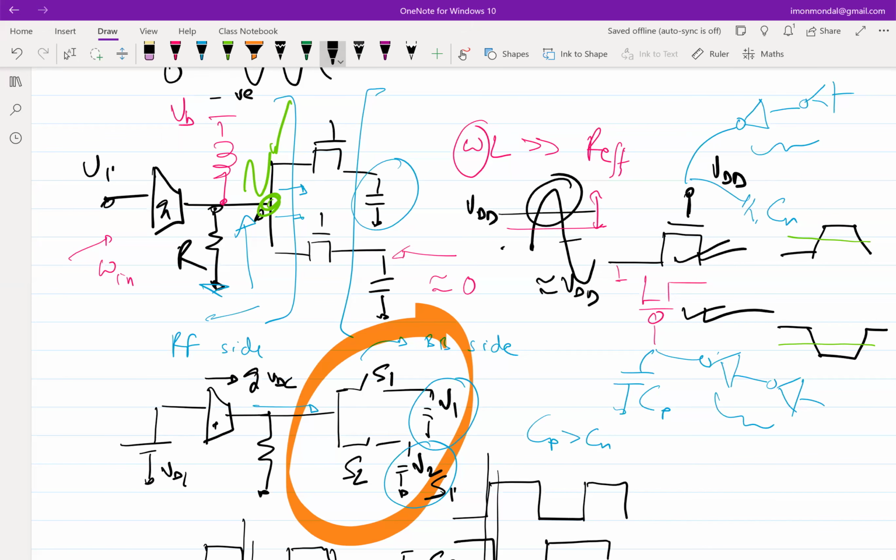Okay, fine. So the key takeaway is that it is better to use NMOS. Having said all of this, you can still use a PMOS transmission gate if you are aware of these things and taking care of them. But simply using it vanilla is a problem. I am not penalizing any of you for using a transmission gate, because at this stage I don't expect you to understand that level of intricacy. It also doesn't always show up in your design, because you are using ideal clocks.